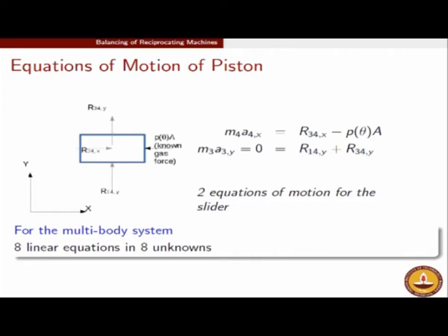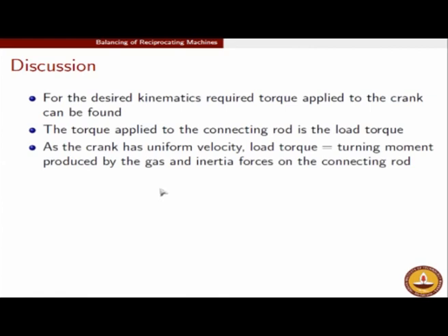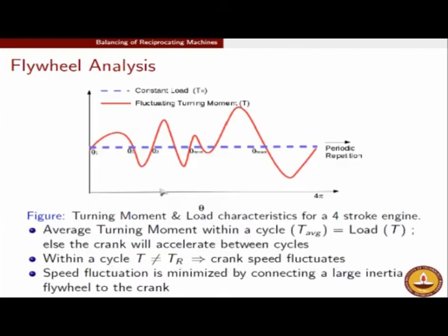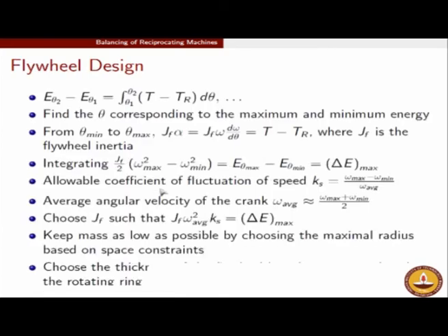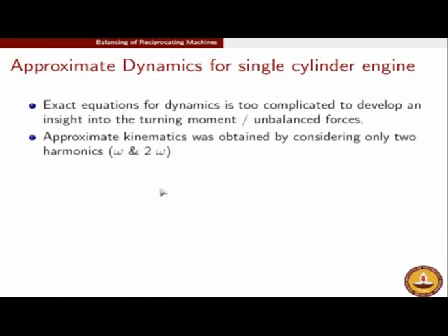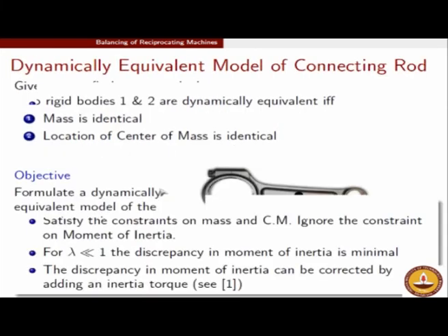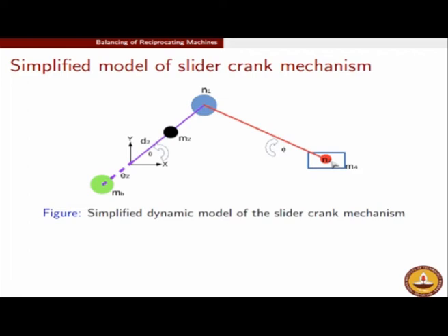Okay, another question. Why is the shaking moment 0? Shaking moment is 0 as is borne out from the simplified analysis. In the simplified analysis presented here, you will see that there are no inertia torques in this simplified model. In the simplified model, the rotary parts are completely balanced.